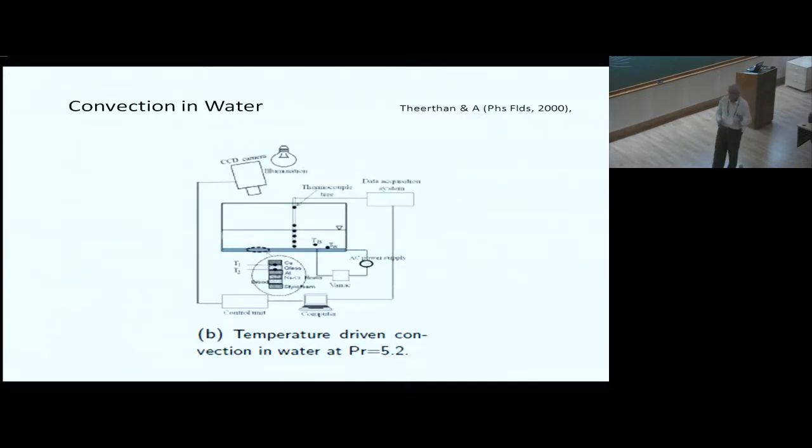The other technique is the standard experimental setup where you use heat, so basically you have a heated plate here. You start with the insulation, and if you want to measure the heat flux, one technique is to use something like a glass sheet and measure the temperature difference across that glass sheet.